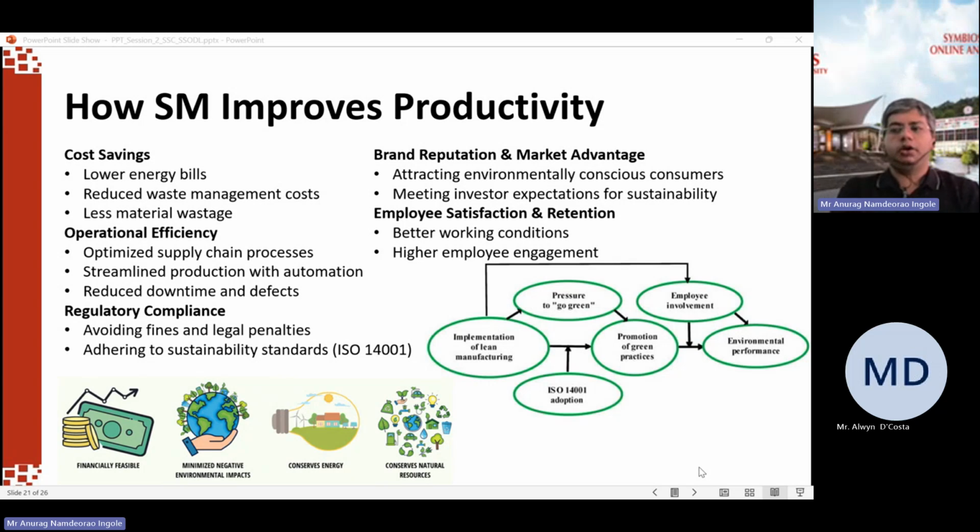Whenever you want to implement lean and optimize your process, the first step is to map the existing process that you have at hand. The current process which you are following, you need to map it first. Are you aware of what all activities are happening in the manufacturing and processing of your product? Do you have visibility in that process? Once you map that process, you start looking at what the value added activities are, what the waiting time is, what the processing time is which actually adds value, and what the non-value added time is, and then you try to reduce the non-value added time, which is nothing but your waste.